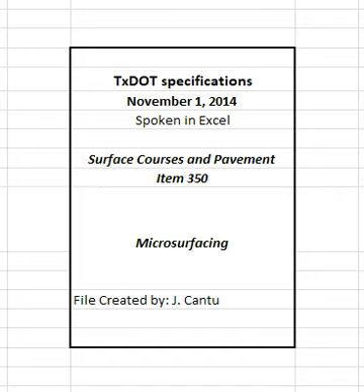2.1 Cationic polymer modified asphalt emulsion. Provide CSS1P in accordance with Section 300.2.4, Emulsified asphalt. 2.2 Aggregate. Furnish crushed aggregate from a single source meeting the requirements of Table 1 and Table 2. Determine aggregate gradations for mixture design and production testing based on the washed sieve analysis given in Tex-200-F, Part 2. Aggregate from sources listed in the Department's Bituminous Rated Source Quality Catalog, BRSQC, are pre-approved for use.